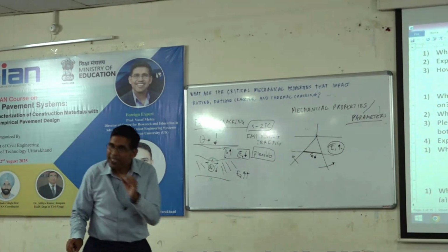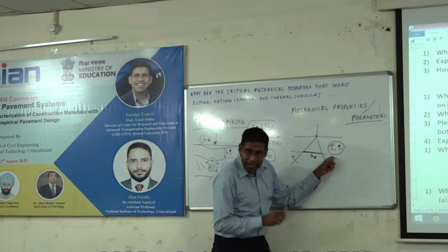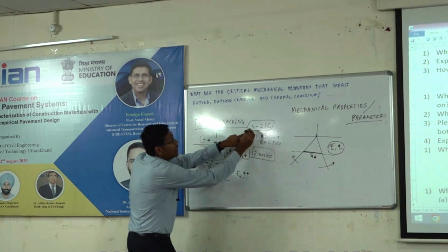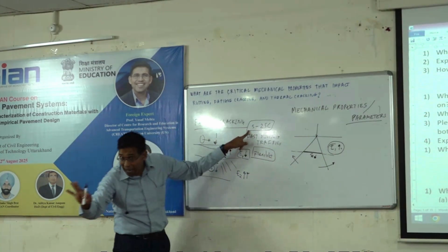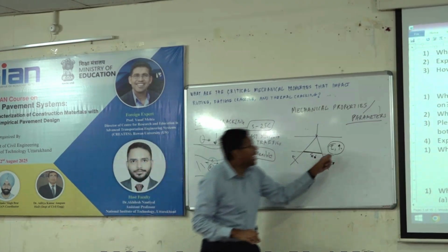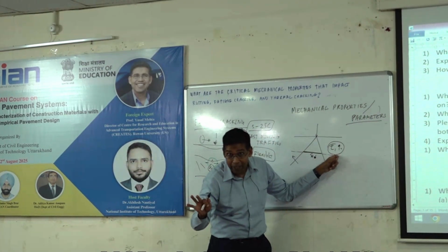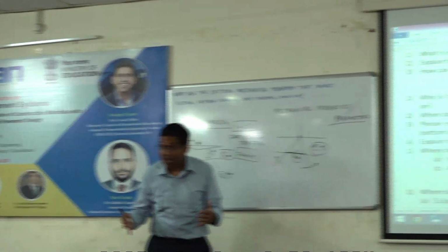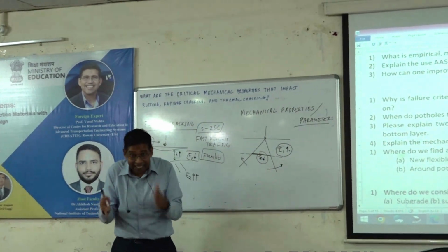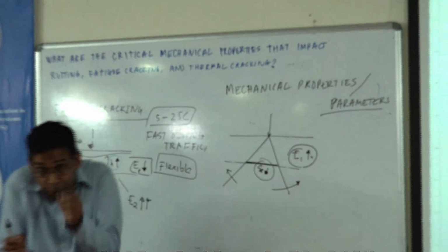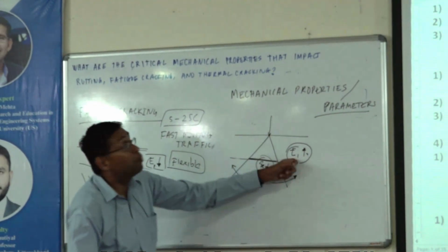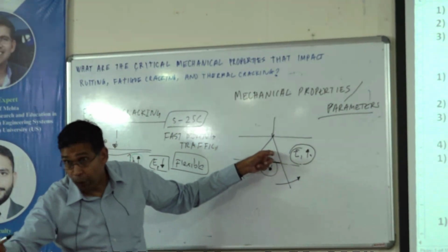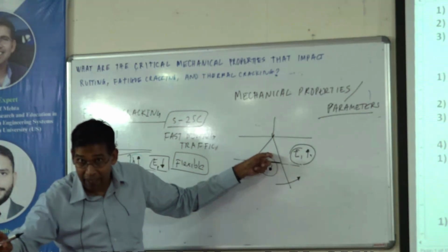Let's look at this. There are a couple of things. If I can increase my E1, remember, I'm only working in this temperature range, correct? I cannot increase E1 that much to drop epsilon T too low. My material cannot do it. I don't have this magical material that between 5 and 25 C will just become so high that it acts like steel. Not possible. My asphalt cannot handle it. Does that make sense?